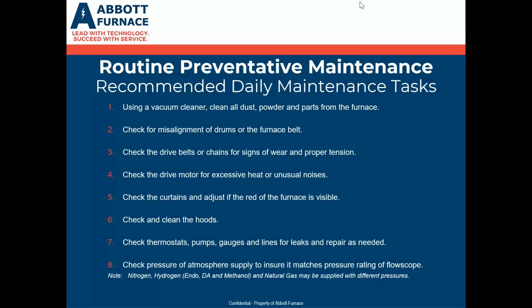Also, the drive motor and the gearbox: make sure there's no excessive heat and no noises on the gearbox. If they do have it, it's probably time to change it on a scheduled shutdown instead of having a catastrophic failure. It's going to keep you down for a while.